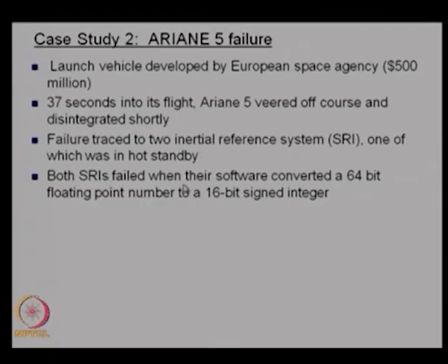Both SRIs failed when their software converted a 64-bit floating point number to a 16-bit signed integer. This was the basic cause of the failure. There was a conversion of a 64-bit floating point number to a 16-bit signed integer, which was not planned in the system, or they never expected this kind of conversion, and since the interface could not accept the data, there was a failure.